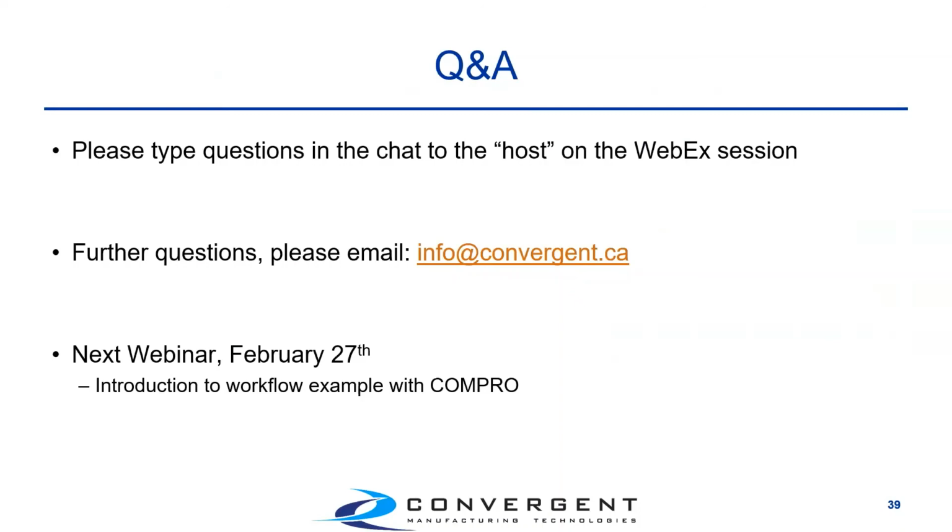One of the questions was related to some of those advanced simulations, the ACP, the AFP, additive manufacturing. Are those publicly available with COMPRO, that anybody can buy right now? The capabilities are there, but in terms of streamlining, for example, in the case of AM, you have the deposition that's happening. That means that the elements need to be activated, and that's not automated yet. So there are some manual steps that need to be done.